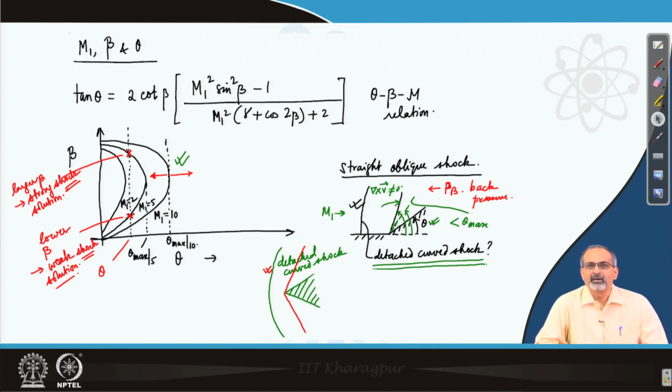As you know by now, if you were to make the sharp wedge blunted, then almost by default the shock would become detached and curved anyway. So, that is what we call the blunt body bow shock. However, in the case of a slender sharp object, very often we might have an attached shock, but not always. So, that is something that we have to keep in mind.